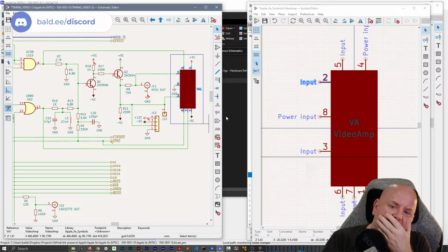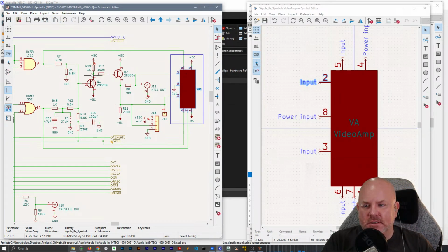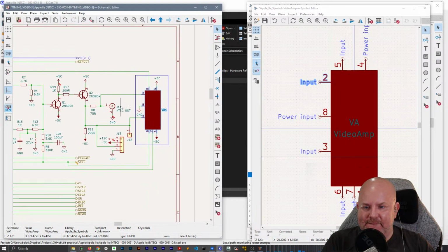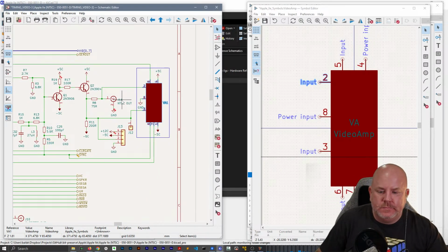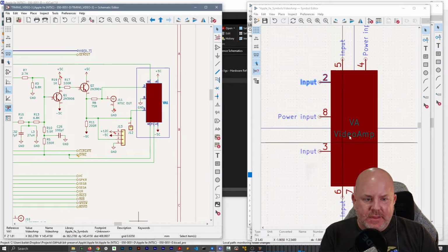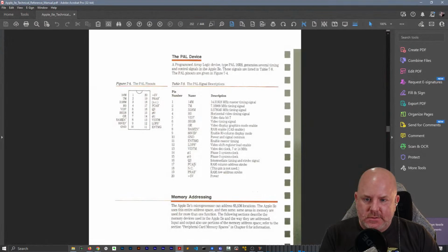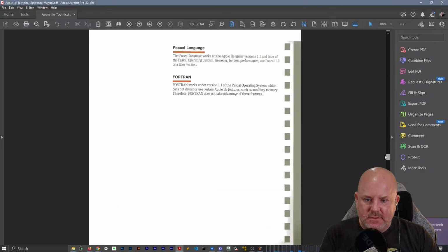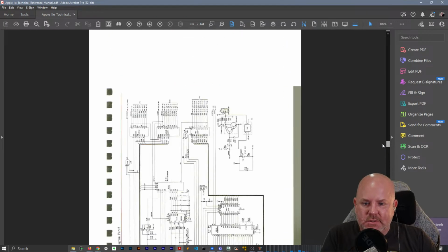Huh. So I wonder if this is actually, because this is clearly the shift register output. So this is the luminance information. Here's our sync pulse, the color burst. I wish I knew what was inside of this box. I wonder if the manual has this.